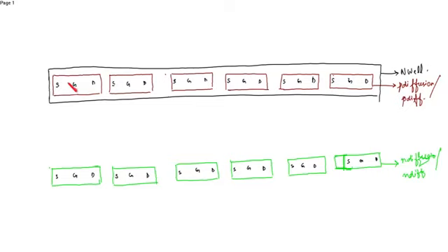Now the gate of PMOS 1 is connected to the gate of NMOS 2 in our transmission gate. So we connect. Okay. Similarly, for transmission gate 2, the gate of PMOS 2 is connected to the gate of NMOS 1.